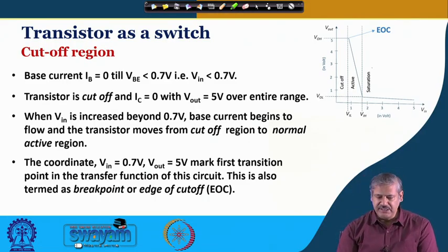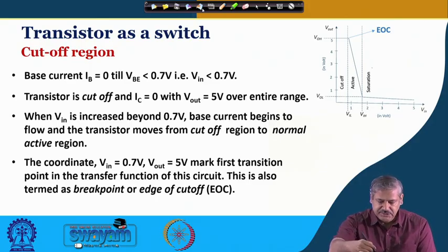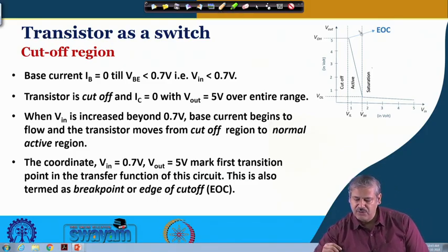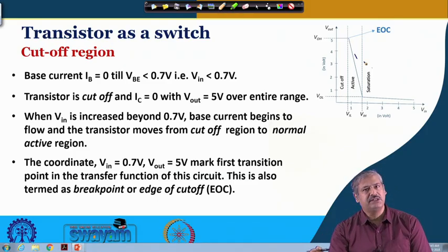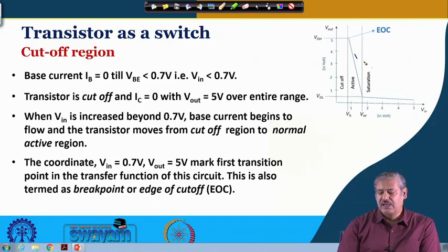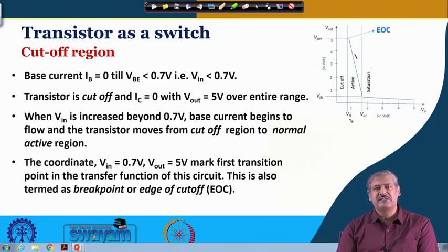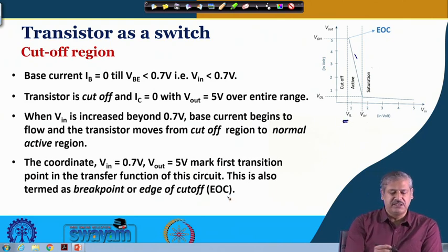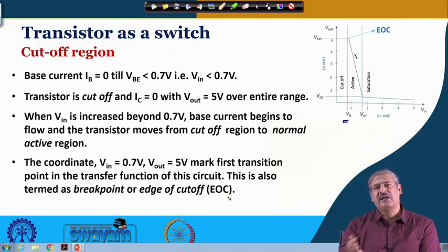The first thing that we shall try to get is at which voltage this fall starts occurring. In this particular case it is very simple: this VIL is nothing but the voltage when it comes out of the cutoff region and enters the active region, and based on the values we have already taken, it occurs at 0.7 volt.